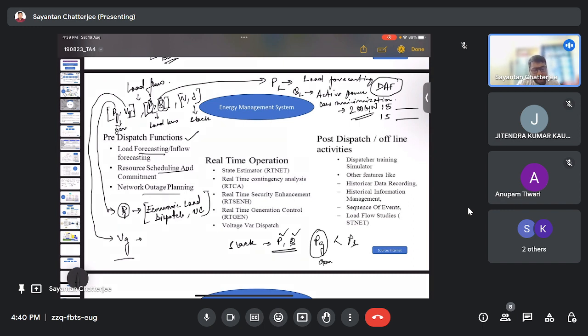So yes, batteries will be considered as PV buses in the present load dispatching problem, like all the wind power plants and solar power plants. But sir, our concept of storage is not continuous. Whenever it is required, it will be switched on. So why are we not considering the battery storage as a slack bus?